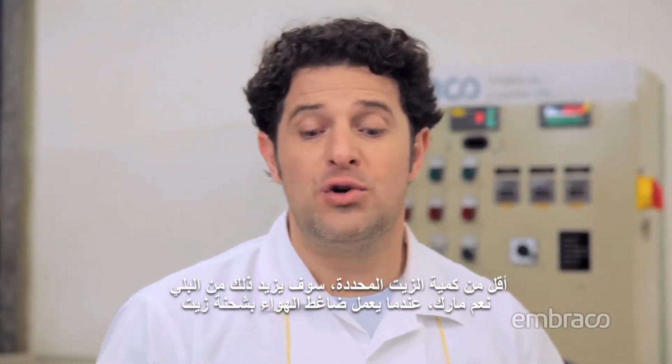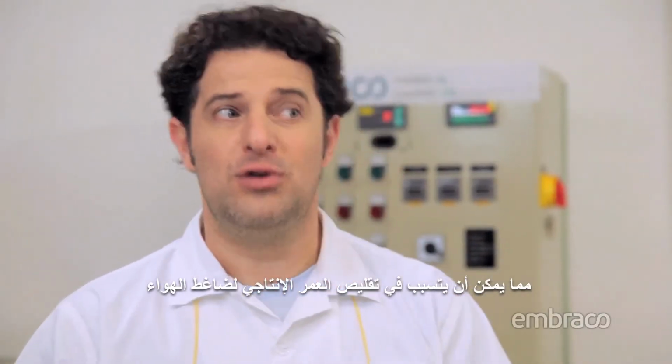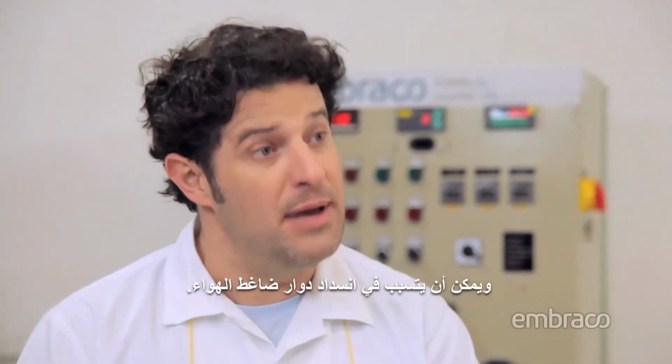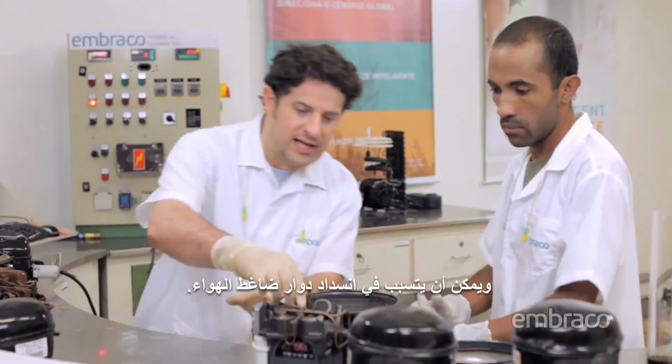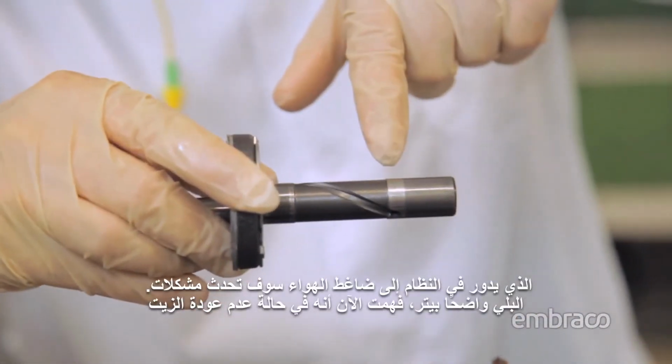Yes, Mark, when the compressor operates with an oil charge lower than specified, there will be increased wear, which can reduce the useful life of the compressor and could create a locked rotor situation. Take a look at this wear. The wear is really visible, Peter.